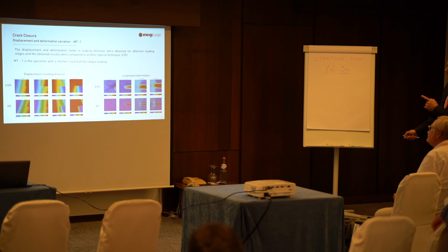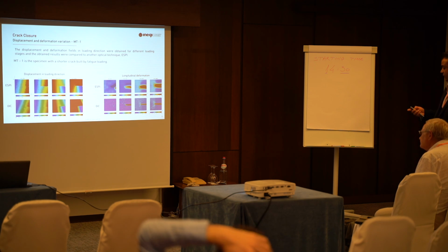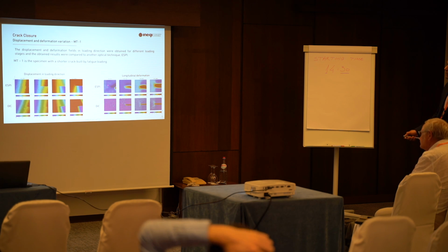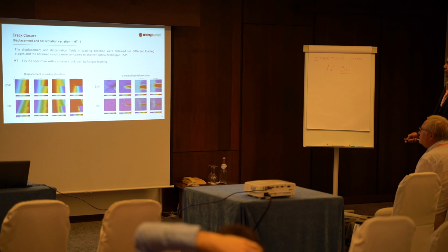Once we load it with further values, the crack starts to show, and this is the verification between both. This is also the same when we have the deformation. So this is the plasticity induced by the fatigue. We cannot ignore it because it's done when we open the crack. Also here, in the first load stage, there is no crack visible, because we don't have the deformation visible either.